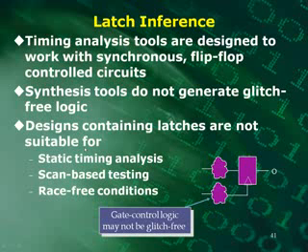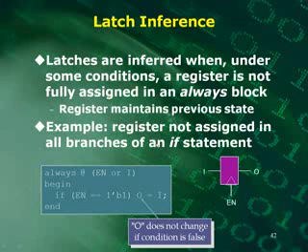Okay, designs containing latches are not suitable for static timing analysis. Okay, when I say latches, I'm not talking about flip-flops, I'm talking about latches. And they're not suitable for scan-based testing and race-free conditions. So stick to combinational and flip-flops. Latches, you're going to need to know what you're doing there. They're just problems.